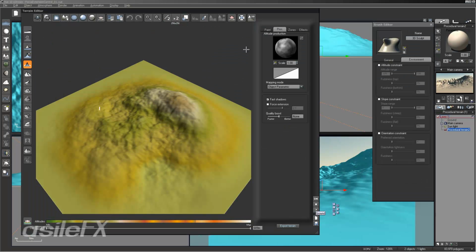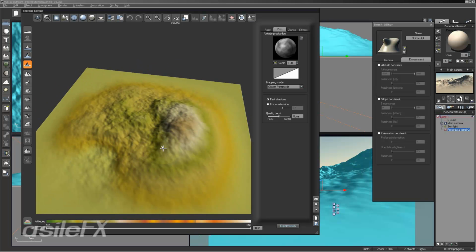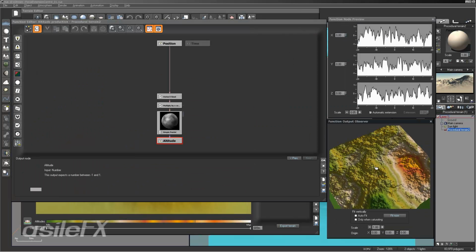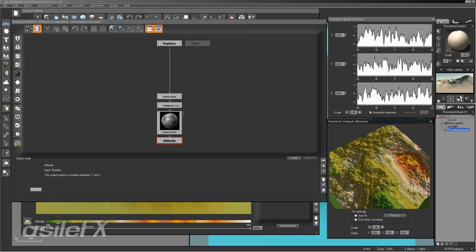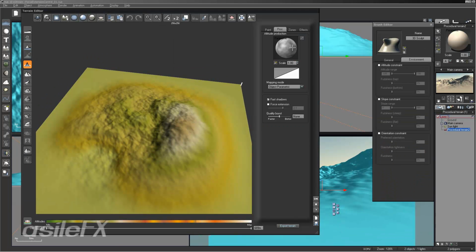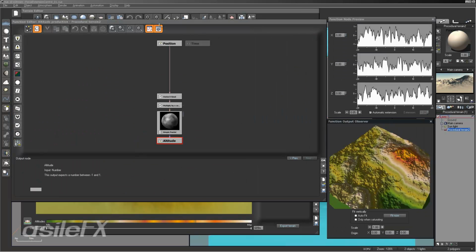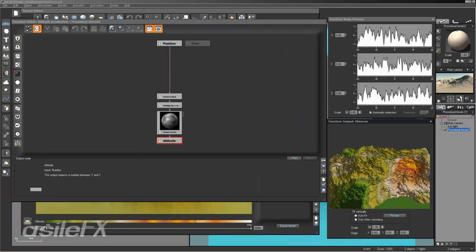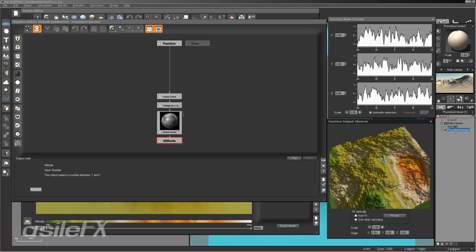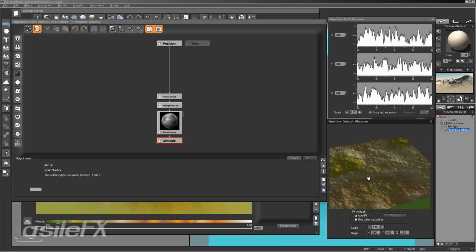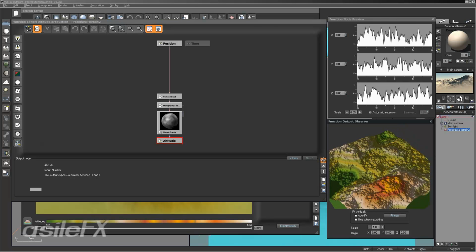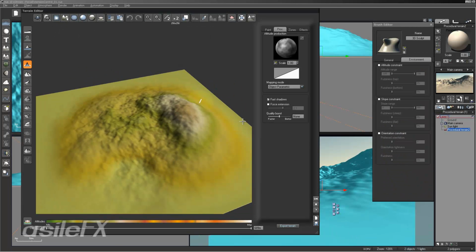If we go back into the terrain editor and take a look at the coloration, because of the force extension, the color map for the height that really gives us a preview is more limited, and also doesn't match the function output observer if we go to edit the altitude production. You can right click, go to edit function, or you can control click on this to open up the function editor, and with the output observer open, we see the actual elevation being put out. If we turn on auto fit, it'll be a little bit closer, but it's still going to be off and not going to match what we have in the terrain editor.